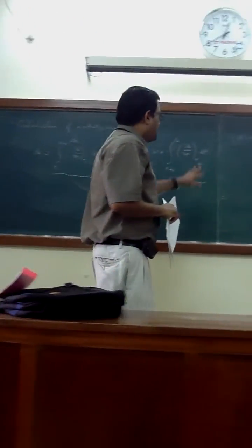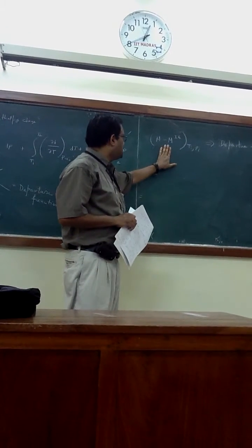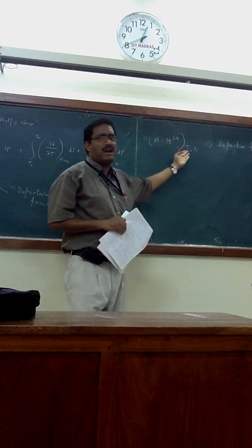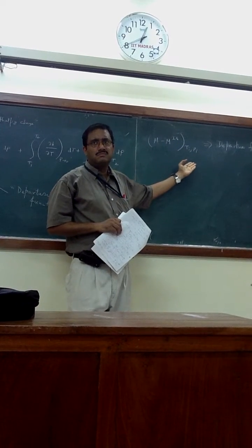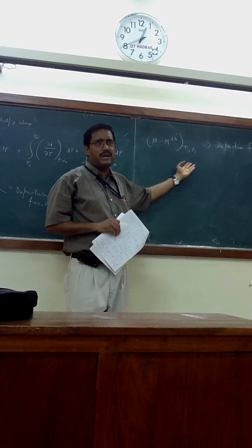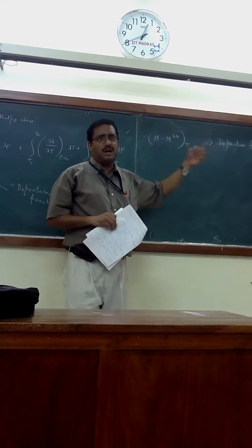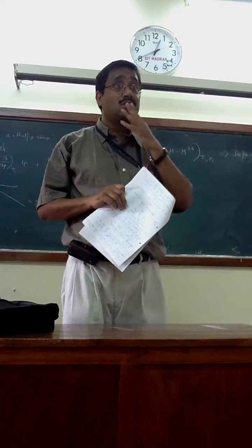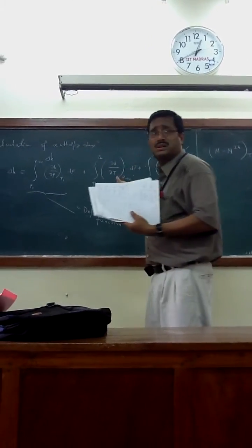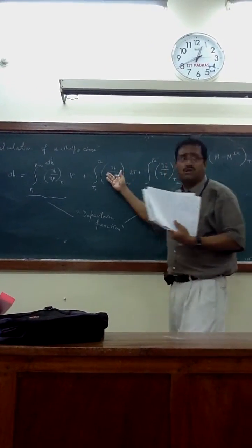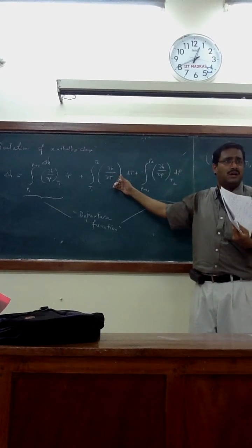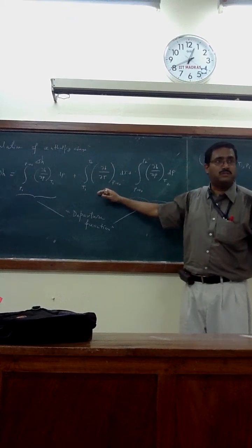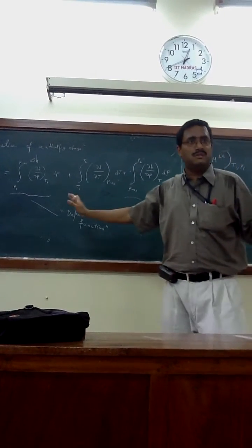Departure means how far your property is from ideal gas at a temperature T, P. But yes, sir, why are you not considering the middle term? I cannot evaluate it by departure because it is known. It is Cp ig dT. It can be evaluated. Already you have done it. It is having no problem now. This part is solved.